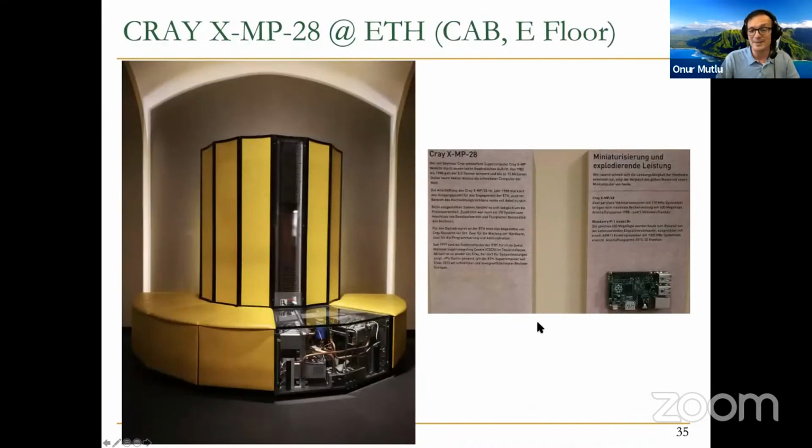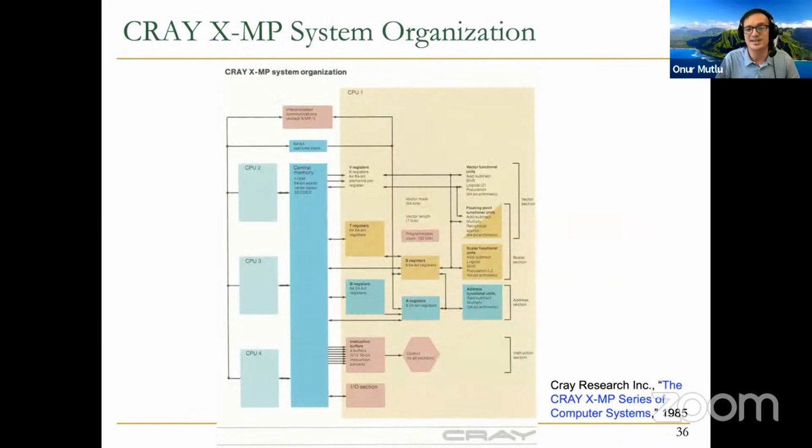Okay, I would also recommend that you go and take a look at the later version of a Cray machine, the Cray X1. You can find some information about it also. And you can see that it looks like Cray 1 as well, except it's a better version of Cray 1, if you will. You can see there's a vector mask register, 64 bits, vector registers over here. Memories are also larger than Cray 1. But you can see the basic structure is very similar to Cray 1. Okay, there's scalar functional units, etc.